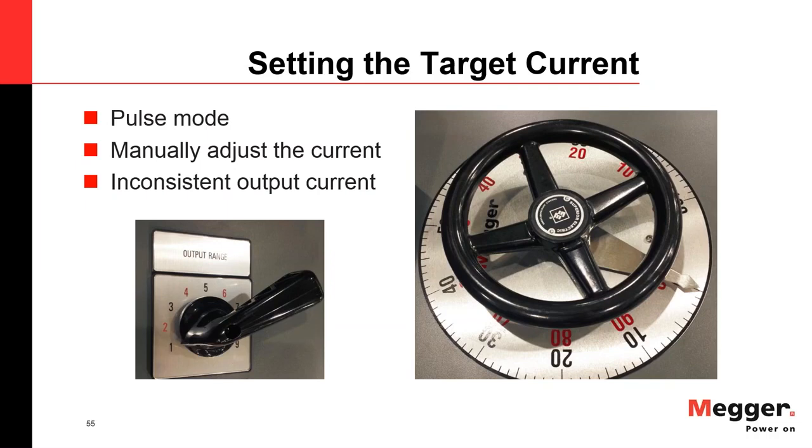That also means, because this classic setup with the variac and the transformer is relative, you will see there's no voltage or anything, it's just percentage, 10, 20%, and then the red numbers, because this one is a buck boost, 100%, 80%, and so forth. If you hook up a different breaker, specifically if you change also lead size or lead length, the same setting will give you a different current.